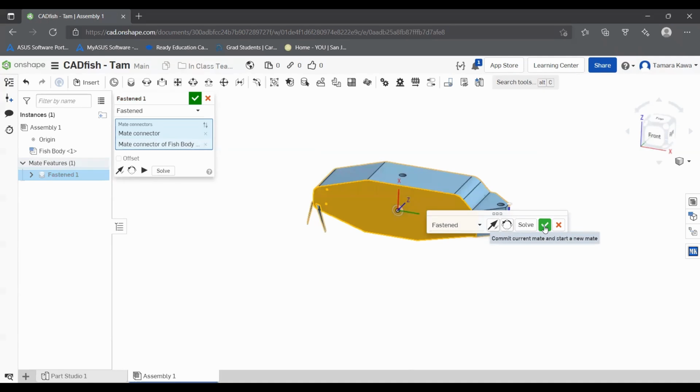So, before I click the check, I'm going to show you the reason this is so contentious for a lot of us is because those of us who worked with the CAD students last season know that this specific mate type became the most frequently used mate type. And I think you can understand why that might be a problem. Because this is a rigid, fixed, offset is controlled, position is controlled, angle is controlled type of mate, this has very strong abusing power. Because it doesn't just act as a coincident mate. That's a misunderstanding. This fixes it. This is not going to move.